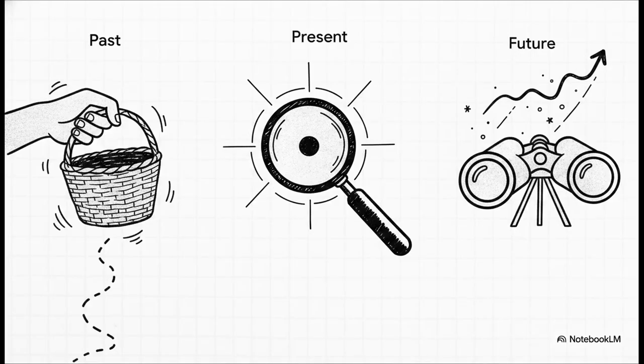So let's break down those 3 letters because they're absolutely crucial. They represent 3 specific mathematical ways the controller calculates how to fix the error. First up, proportional gain, or KP. This looks at the present error. The bigger the error is right now, the harder it pushes. Simple enough, right? Next is integral gain, or KI.